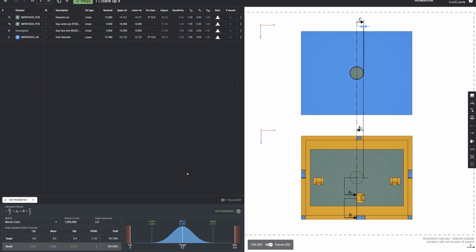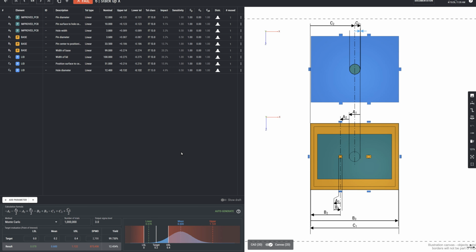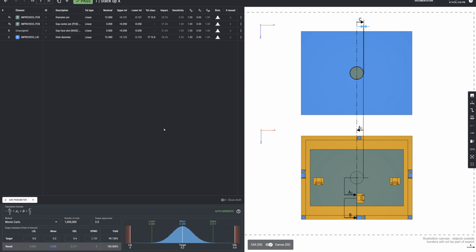Here you'll see the updated tolerance calculation and the benefits of this. So recall the first stack, we have a lot of failing samples. And we also see that we have 9 parameters that we need to keep in control. If we look at the latest update, you'll see now that we have removed the number of parameters to only 4. And I think I can see, at least from the visualization alone, that the path is simpler, but obviously the performance is better as well. Exactly. So now we have 0 failing items. All of these parts pass the requirement.